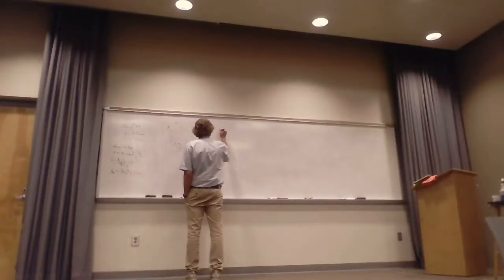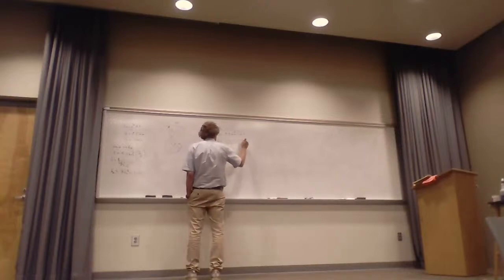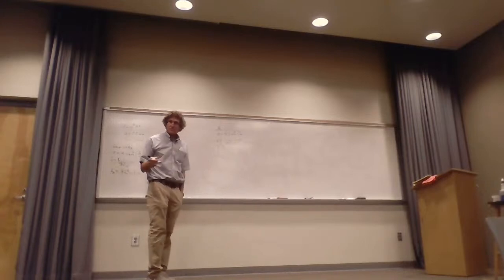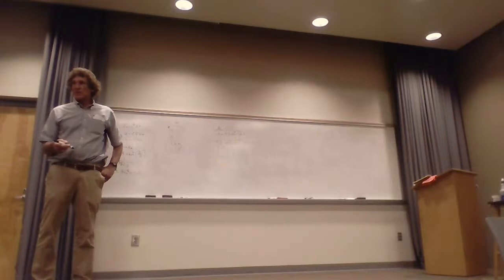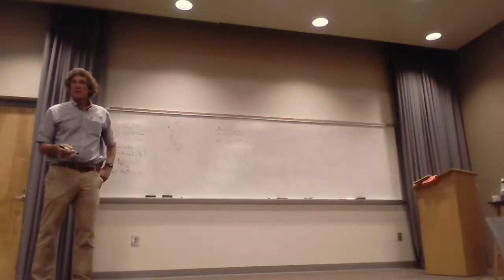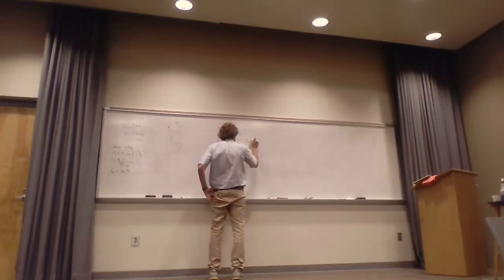And for aluminum, AL, the conductivity is 3.5 times 10 to the 7th, and the units are 1 over ohm meters or Siemens per meter. So therefore, the skin depth of this is 1 over the square root of pi f mu 0 sigma. You've got sigma there. You can give me that one. Do y'all agree with this? We're just getting skin depths, right? Not much difference. 9 micrometers.